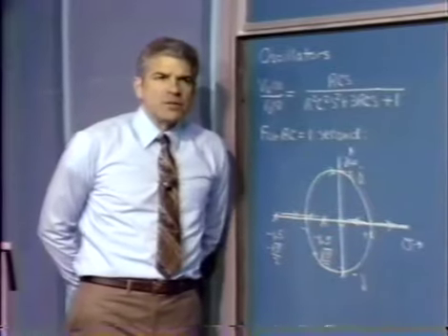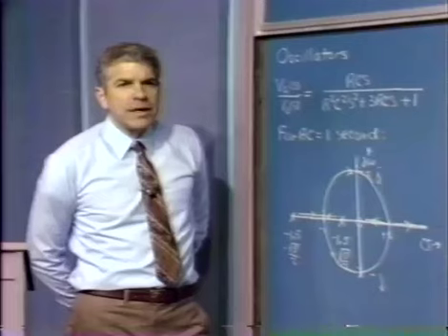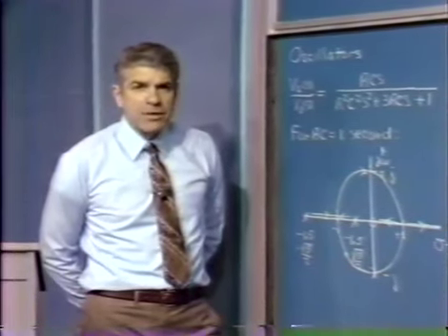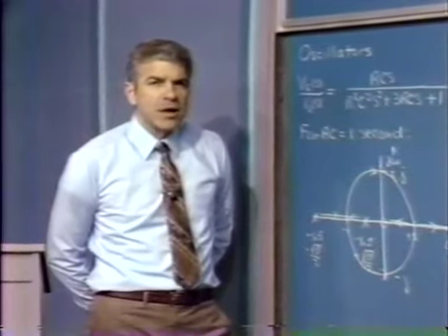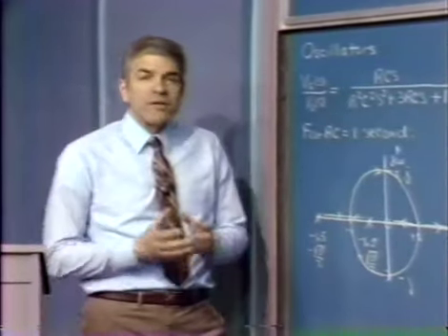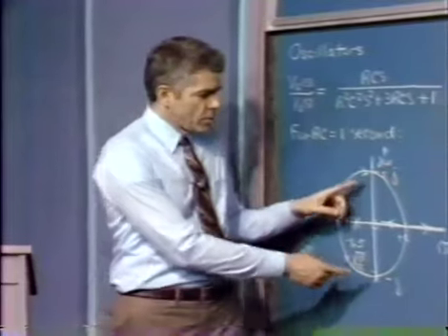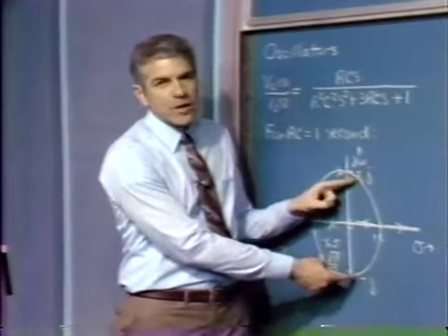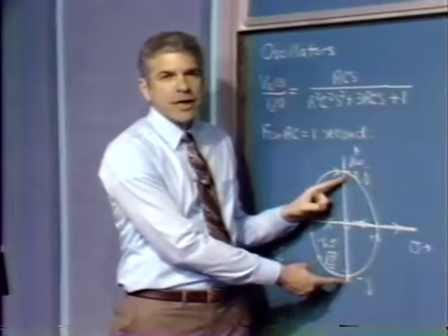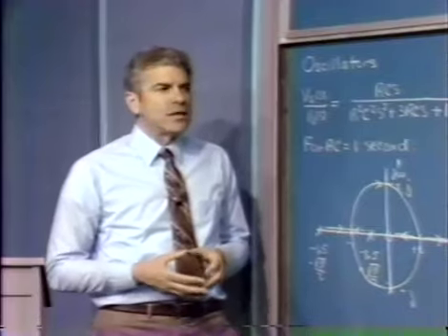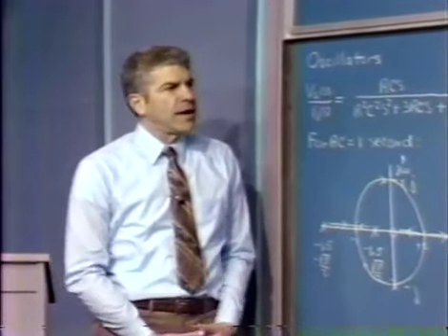Well, when we go to do this, we have to worry somehow about stabilizing the amplitude of the oscillation. If we simply build up our linear system, of course, we'd never get things precisely right. The poles would either be in the left half plane or they'd be in the right half plane. We would never be able to get them precisely on the imaginary axis. So we have to somehow take care of that fact.